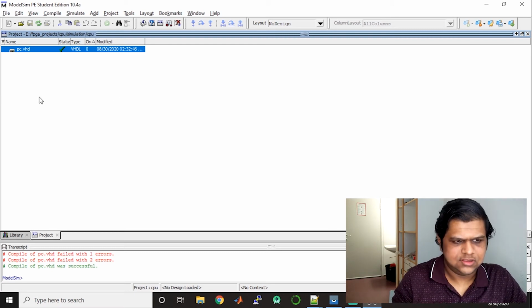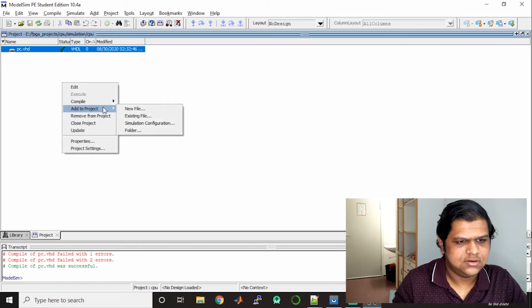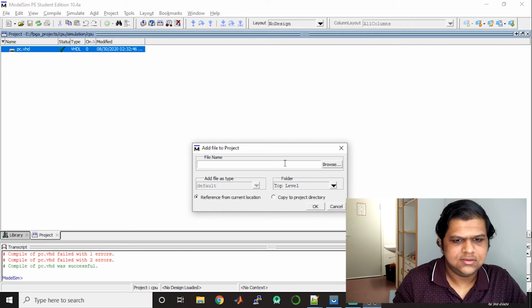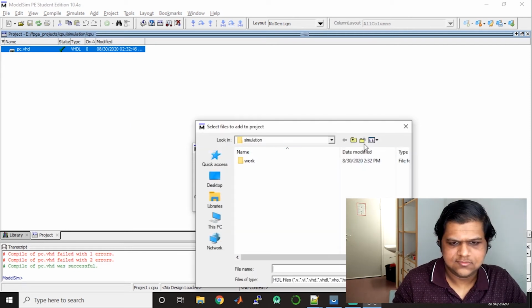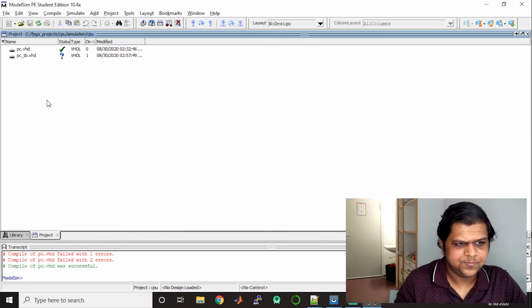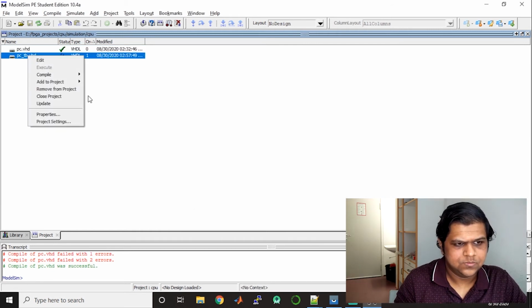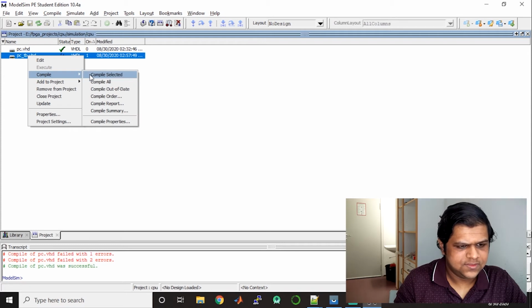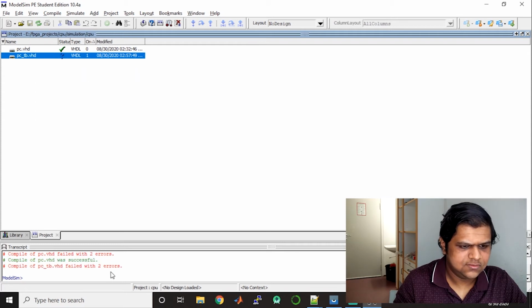So in ModelSim, just right click, add to project, existing file. Let's browse to our test bench. Compile selected, and we have 2 errors.